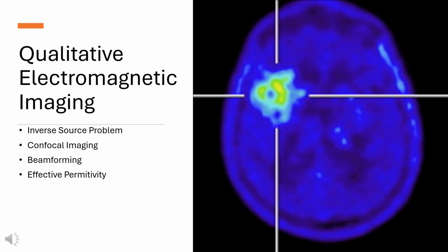This approach simplifies solving the inverse scattering problem by treating each scatterer, such as a tumor or stroke, as an electromagnetic point source. Regarding the multistatic and near-field imaging characteristics of the imaging setup, to reconstruct an image we need to apply a focused beamforming algorithm such as the confocal beamforming algorithm. For this, the first step is identifying focal points to calculate the energy pattern of the reflected signal at these points, which for the multistatic imaging algorithm will be done by coherent signal integration.